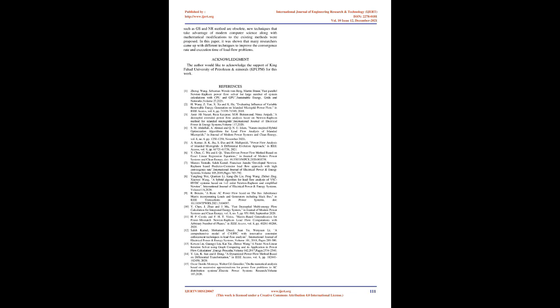To check the validity of this statement, the author performed this method on multiple test systems along with a 2383 bus system. The simulation results of the proposed method were compared with the obtained results of CPF solver in MatPower, and it was shown that the runtime is significantly reduced. In addition, the proposed method is robust and can adapt to non-uniform changes in loads along with generation reactive power limits.